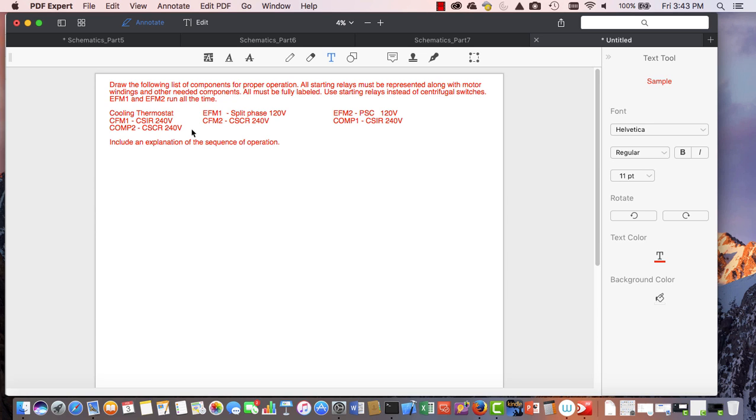Now, we do not use step-up transformers to increase the voltage and the amperage, because in a transformer, if you increase the voltage, you lower the amperage. There's no way this is going to work with a step-up transformer. So the reality is that this is two separate circuits, but there's a single component in this circuit that allows the inside 120 volt circuit to control the 240 volt circuit.